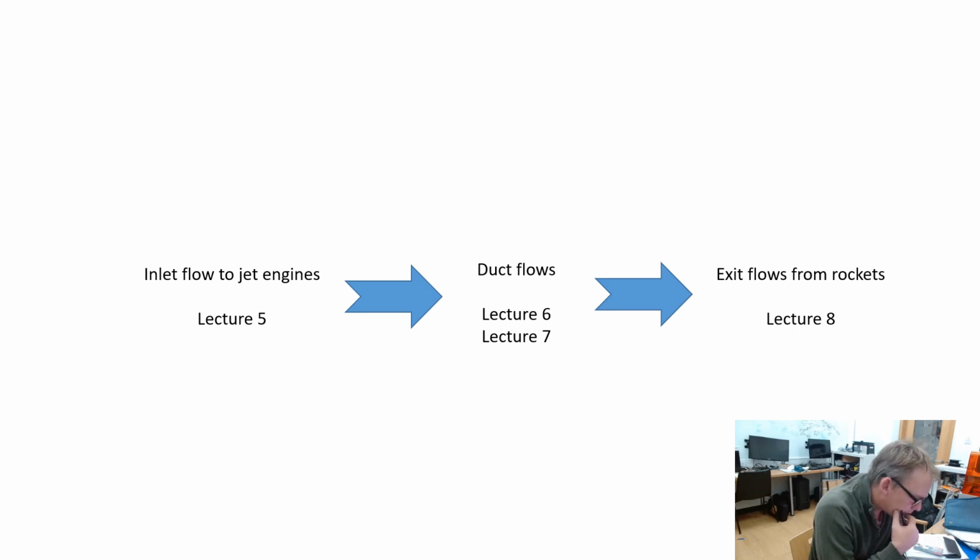the jam in the sandwich, which is the influence of change in cross-sectional area, and the influence of changes of heat, either the addition of heat due to a reaction or condensation or some heat transfer process. So duct flows are what we're going to do today, and in a general sense we're looking at why a rocket nozzle is shaped like this.